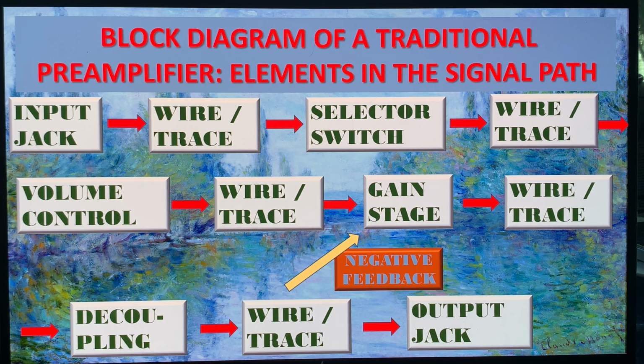So basically this is the basic signal path for every active preamplifier. Now for the exact applications, it can get more complex than this. So this is just the simplest thing. This is what happens when you have a preamplifier with a single active gain stage and there's no EQ in it, no built-in EQ.